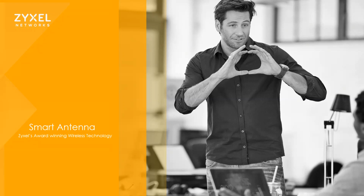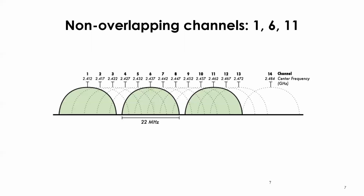So I'm going to take a few slides here to talk a little bit about Wi-Fi RF in general. If you want to know more than what I go into here in these next few slides, we do a Wi-Fi 101 webinar every now and then where I really dig into Wi-Fi and how it works a little bit more in depth. But just to start with here, just in general, when it comes to RF, there's some exceptions here when it comes to things like MU-MIMO, but in general, when it comes to Wi-Fi and radio transmissions, one device transmits at a time on the same channel.